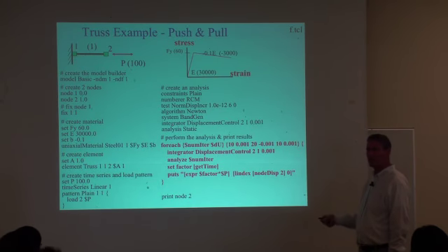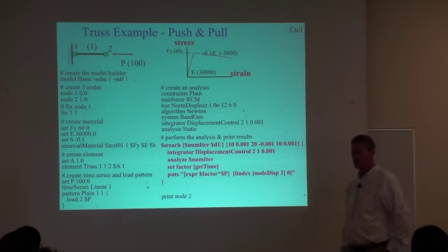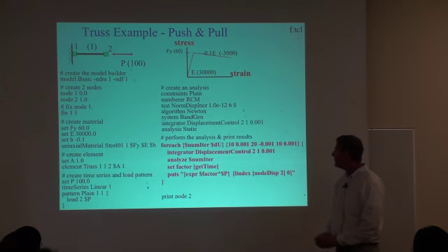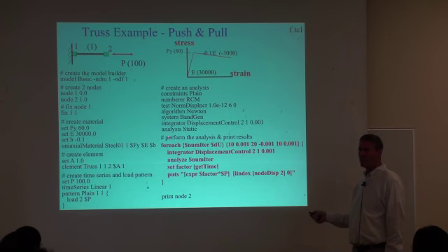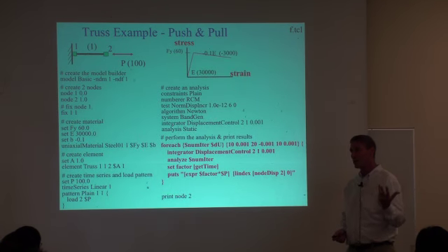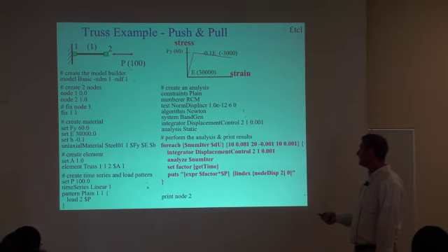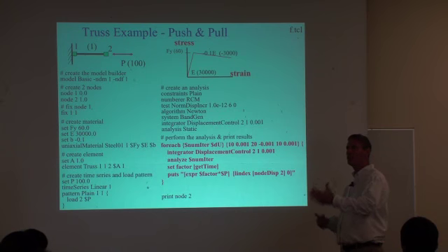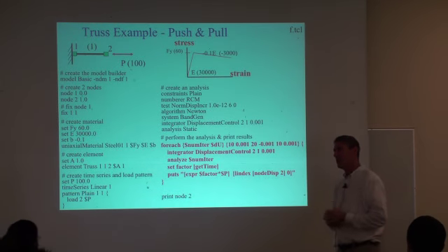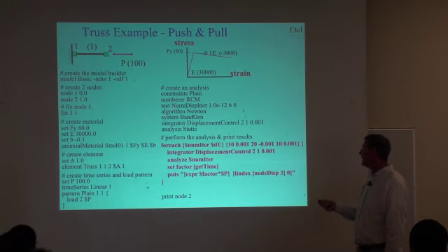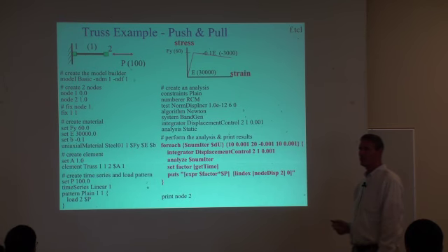Does everybody understand this little script? You need to have the integrator, or both of them? Yes, you do. Before you can construct a static analysis, it needs to have an integration scheme already defined. Any time that you add a new integration scheme, it changes what the current integration scheme is. So I needed this integrator here just to build this analysis. This first one didn't have to be displacement control; it doesn't need load control or anything. It's just that when I come here, this now sets the integrator to be this new one. And then when I do the analyze command, it's using that new integration scheme. Okay?